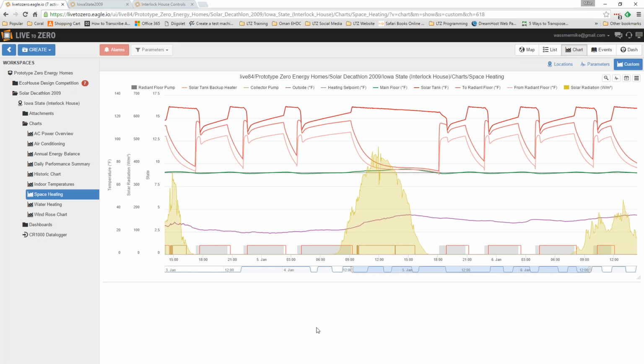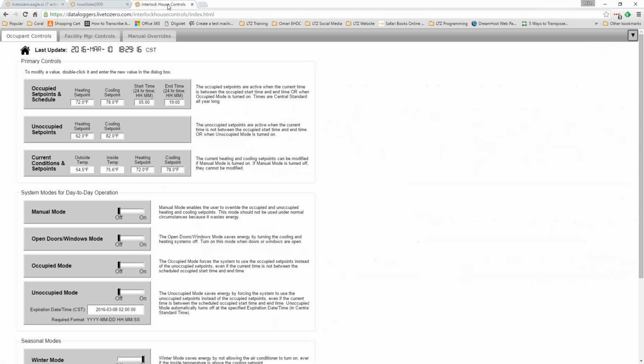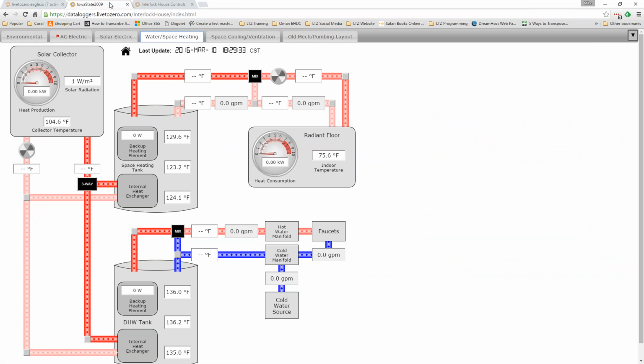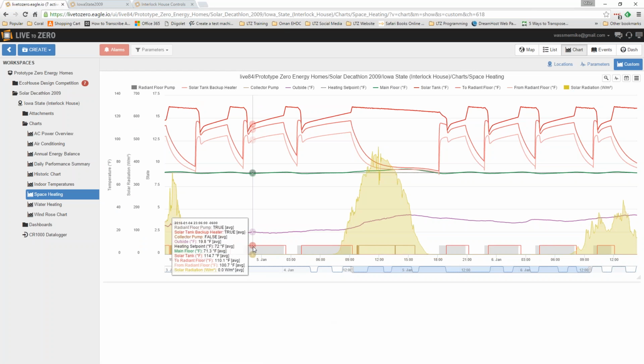That's a widely held myth that the system somehow has to work harder or it's not as efficient. It's actually better. It saves energy for two reasons when you use the setbacks like we're talking about, where it needs several hours. One reason why it's better is because you are letting the difference between the outdoor temperature and the indoor temperature be somewhat smaller when you let the indoor temperature go down. And therefore the building needs less heat to warm up, less electricity. And the other benefit